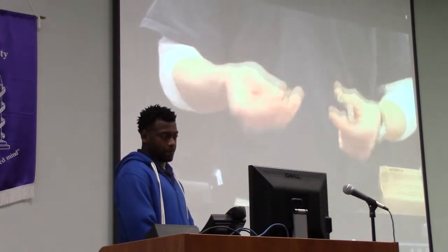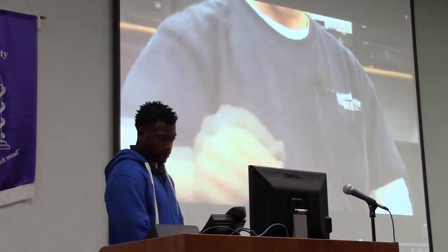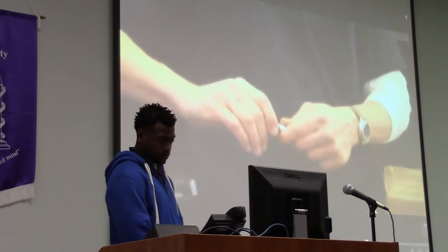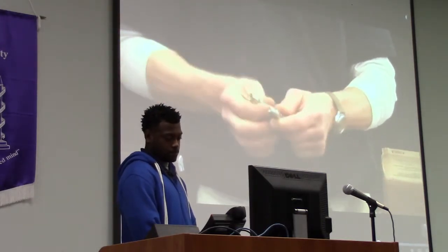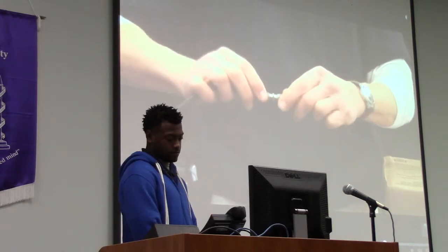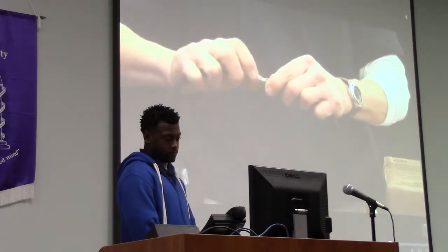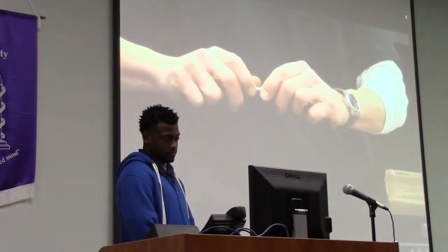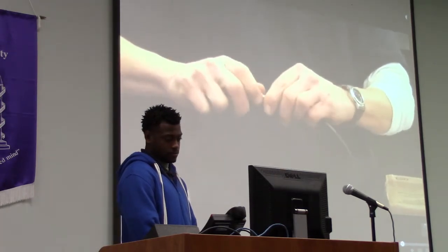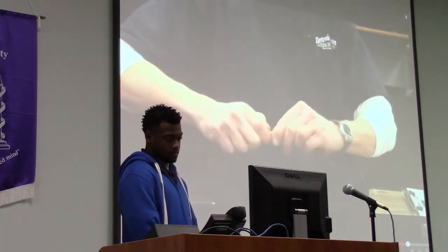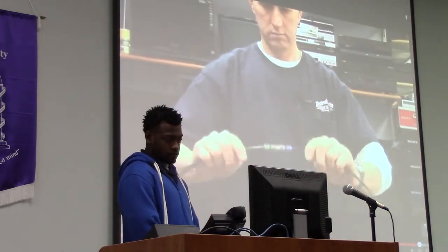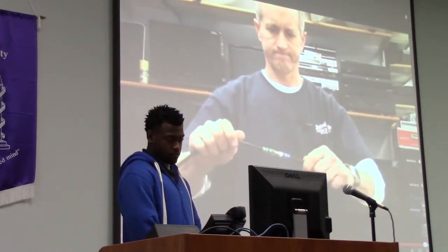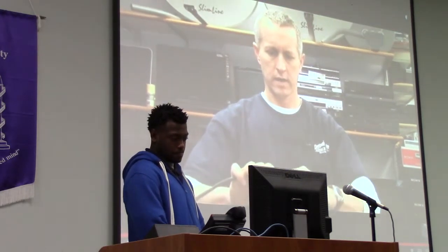And then what you have to get is a barrel connector like this here. This barrel connector goes onto each one. It screws in like that on one side, and then the other side I can put this plug in. And that screws into that side of the barrel connector. And that's a completely weatherproof connection with no chance of coming apart. And that's how to splice a cable.